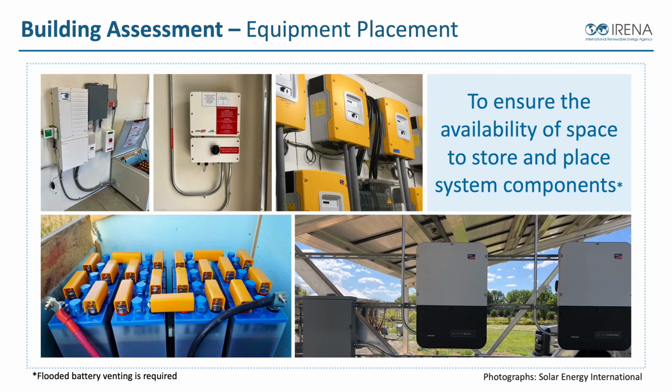If we're looking at energy storage and battery systems, we're going to need a lot more space. Batteries take up a bigger space, may need to be ventilated to the outside depending on what type of batteries they are. Our inverters and our charge controllers and all that support equipment, depending on the size of the system. If it's small, we have smaller components, we can find better places to put it. If it's large systems, we need a big area sometimes to put all this equipment. Also thinking about things like diesel generators and backup systems, or where those go and how these all go together. So space must be really considered.